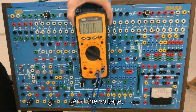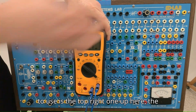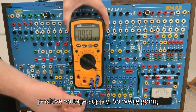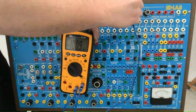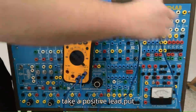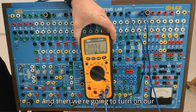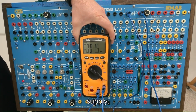And the varying voltage power source we're going to use is the top right one up here, the positive voltage supply. So we're going to take our common lead, put it in the negative terminal, take our positive lead, put it in the positive terminal, and then we're going to turn on our supply.